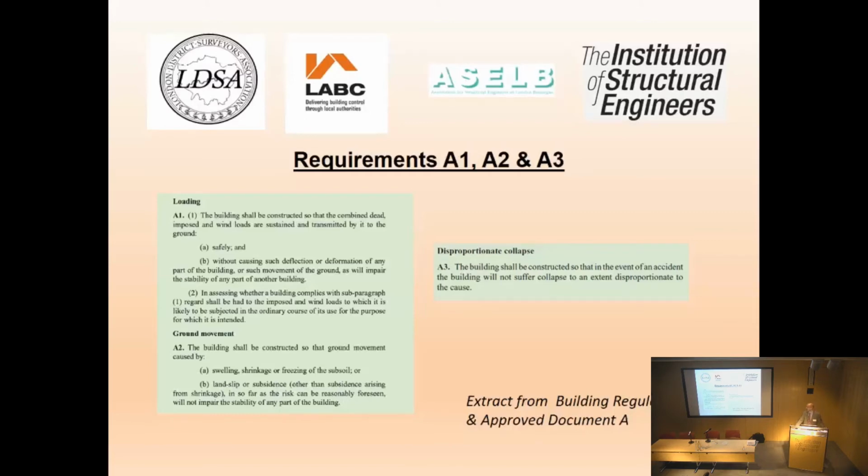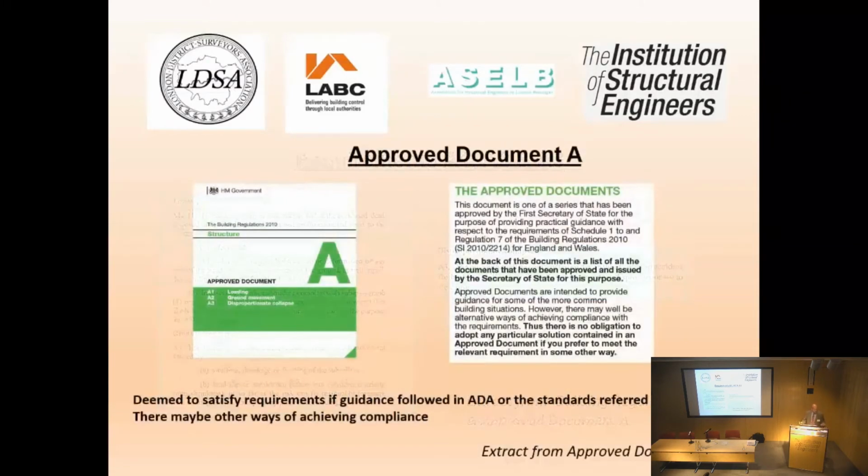And there are quite a number of examples of structures, as structural engineers, that we deal with that are not building structures. The likes of bridges, retaining walls that aren't attached to the building, garden walls and the like, and also what we call in building control exempt buildings. So even structural work to an exempt building does not require a building regulations application. Okay? So whenever we're doing our structural calculations, we need to remember what we're trying to achieve.